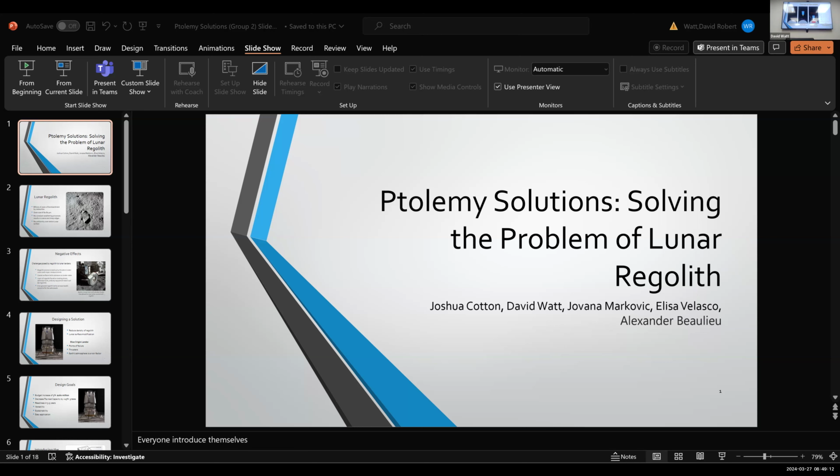Once they open, we'll be releasing our zirconia tarp, which will then act as a barrier that, while not intended to survive the flames of the lander's engine, is intended to spread the kick up of regolith itself and essentially decrease the amount of contact of that kicked up regolith with the lander during its descent towards the moon's surface.